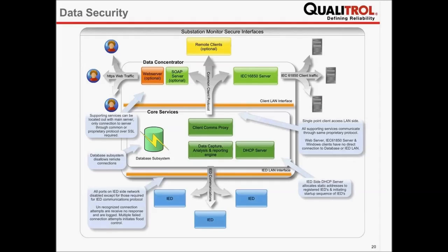In terms of data security, all the IEDs, which are local transformer monitors, should not be accessed directly from the network outside of the utility network. If they want access to this network, they should either have virtual private network access, or they should be directly connecting to the central database, or you can say the substation level database.